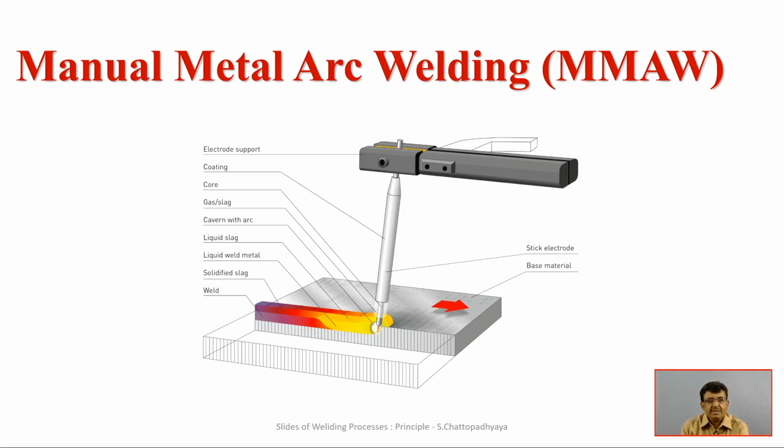So here these flux coated electrodes are there. These flux will melt away and produce the slag, and it will emit some appropriate gases to drive out the atmospheric oxygen and keep a gas jacket outside the flame, so that the molten metal pool at elevated temperature and the heated parent material are not getting oxidized. They don't come in touch with the contamination of atmospheric oxygen.